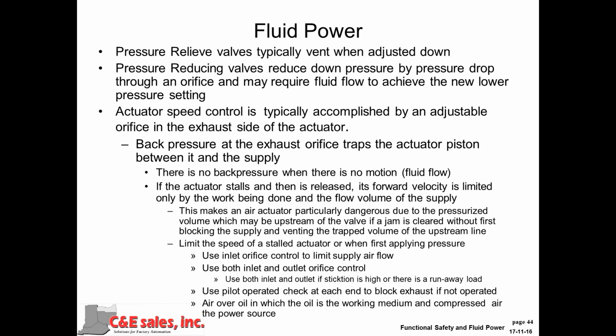If there's a jam, that back pressure is vented, and if the pressure to the other side of the cylinder piston and/or the exhaust from that piston is not blocked by some other method, if someone reaches in and relieves the jam, there'll be a very high acceleration as that cylinder moves forward. So this is one of the more dangerous things for people to do if there's not an assured control of that airflow. Hydraulics are not quite as bad in that they will only advance at the speed at which they have been set. There are a couple different ways to do that.